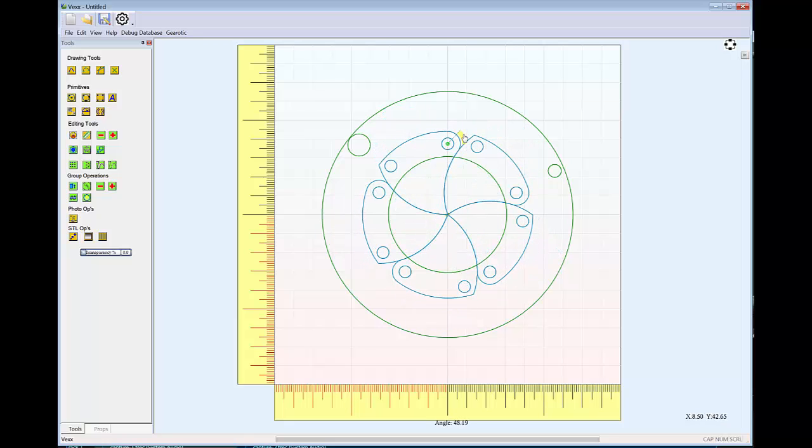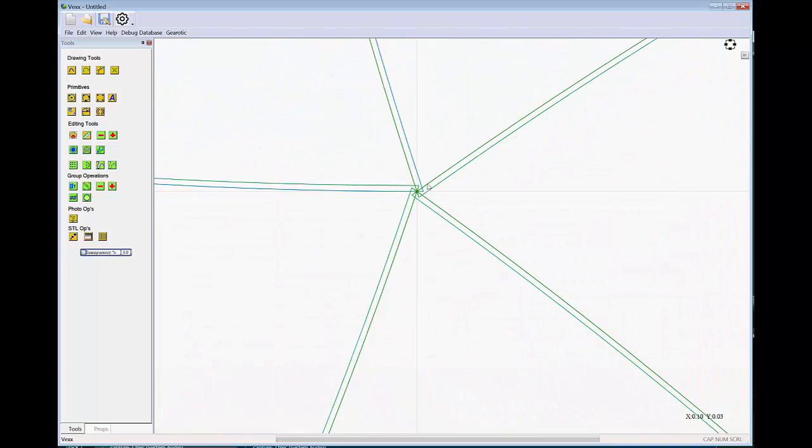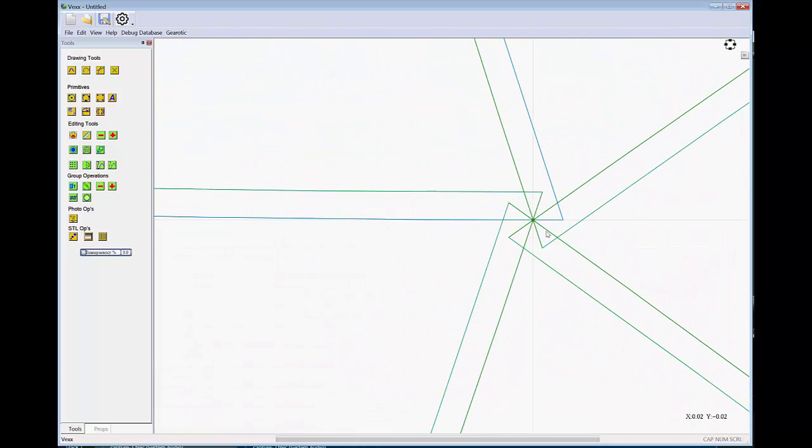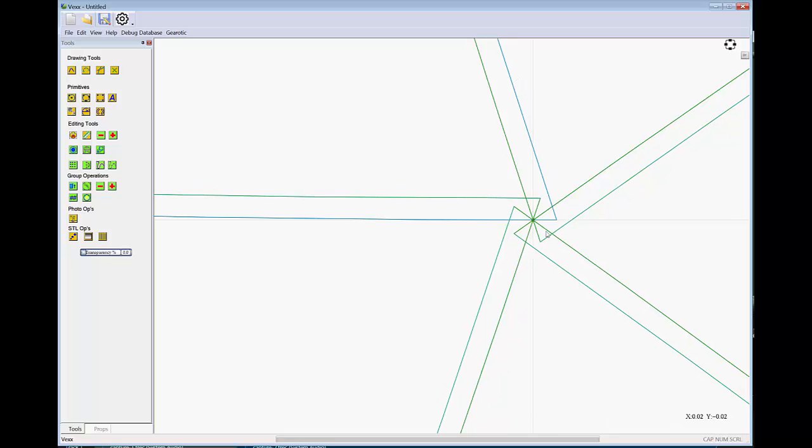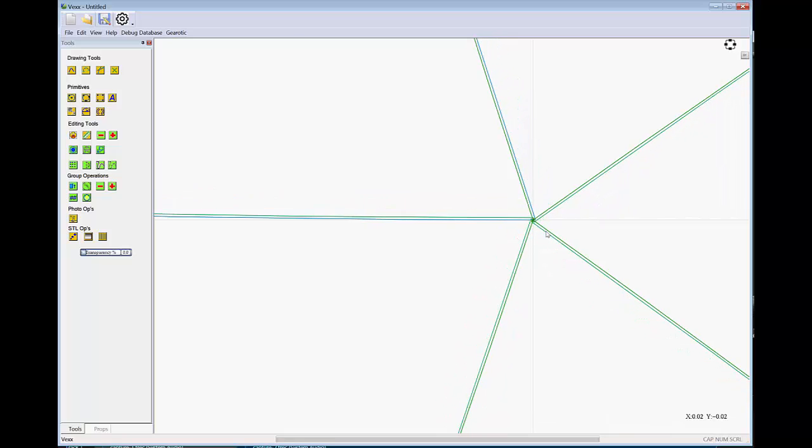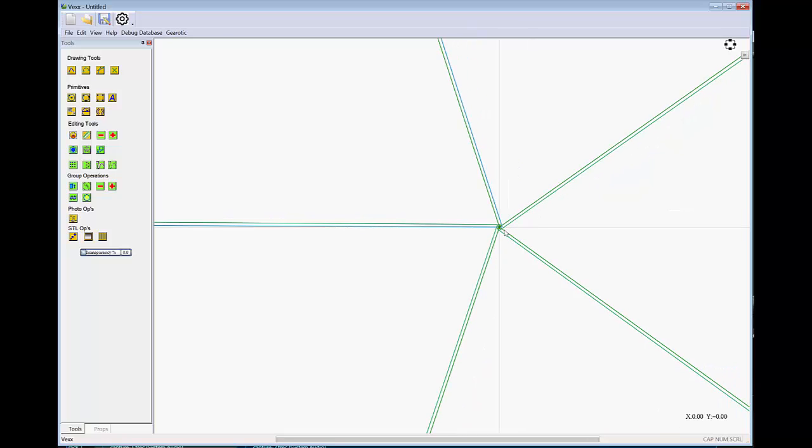Now, if you want to be sure that you're absolutely closed, you can zoom in, and you'll see that we're a little bit off. Using your page up and page down keys will do incremental and small rotations. And the closer you are, the smaller the rotation they will do, to the point where you can get them close enough that the measurement is immaterial.